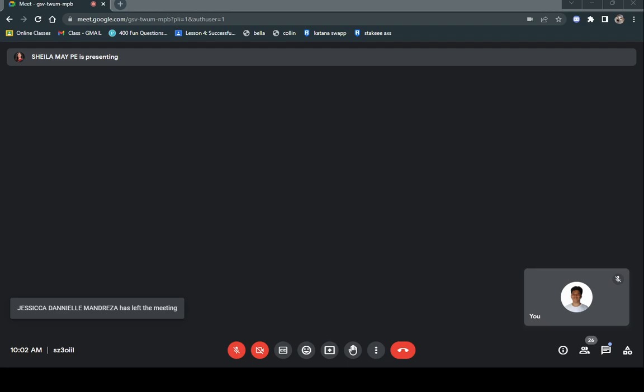VDD is 20, ID is 3.32 times 10 to the negative 3, RD is 2,200, RS is 1,100. So this would be 9.04.